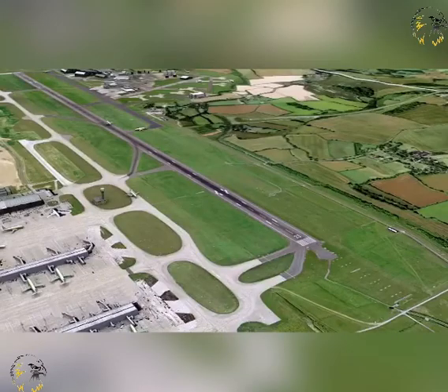A non-instrument runway is one where takeoffs and landings are undertaken visually. These operations are usually defined by reference to ground visibility, or runway visual range, cloud ceiling and daylight considerations. The runway markings will reflect this type of use.